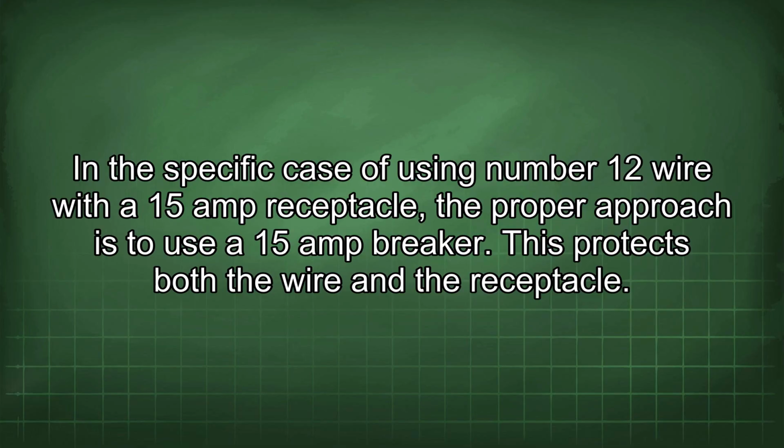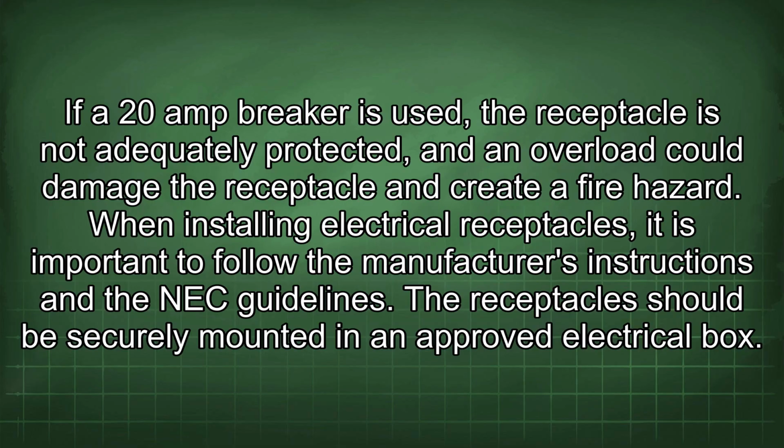This protects both the wire and the receptacle. If a 20 amp breaker is used, the receptacle is not adequately protected, and an overload could damage the receptacle and create a fire hazard. When installing electrical receptacles, it is important to follow the manufacturer's instructions and the NEC guidelines.